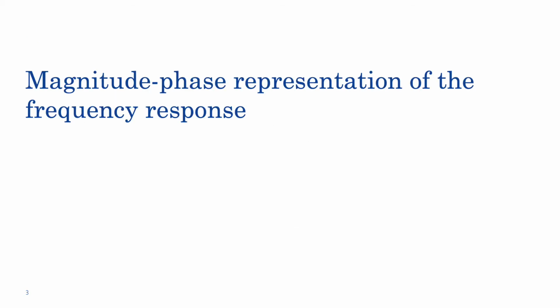We have seen that the frequency domain characterization of an LTI system in terms of its frequency response can be quite convenient because differential equations and convolution operations become algebraic operations in the frequency domain, so quite simpler. Since the Fourier transform and therefore the frequency response is in general a complex function, we need to represent it in terms of its real and imaginary components, or even better, in terms of its magnitude and phase.